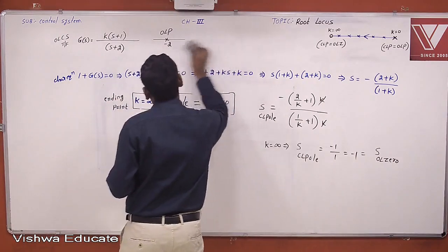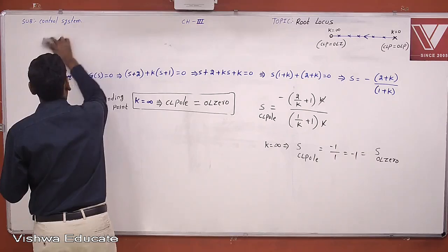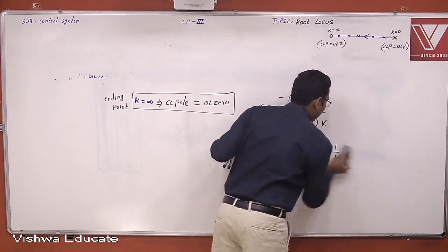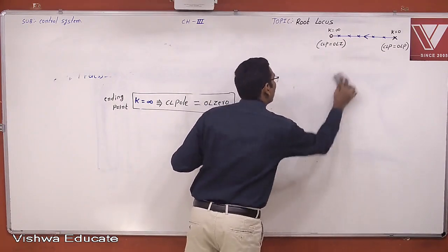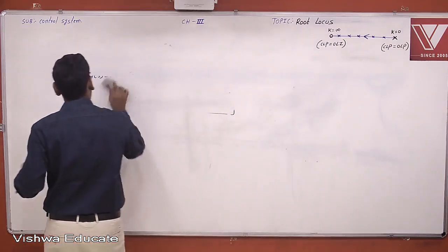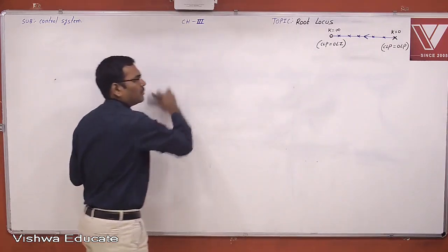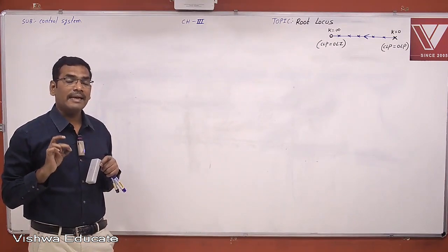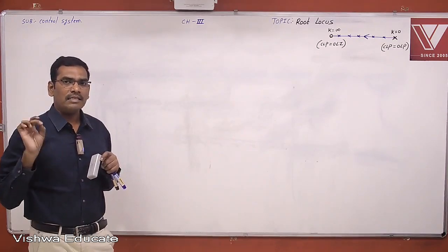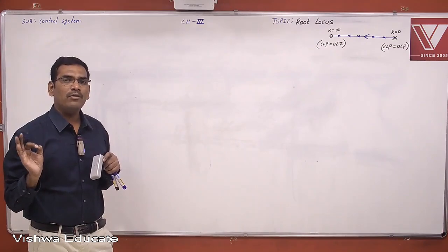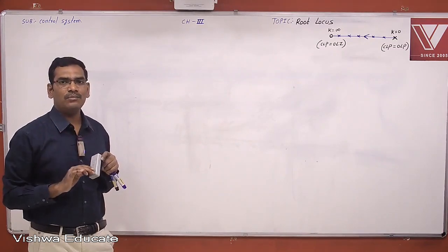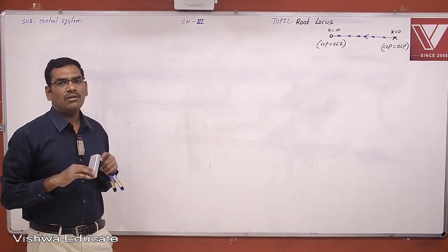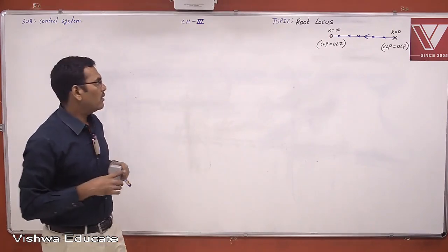So now finally, I think you have an alternate solution for that. Is there any problem in the closed loop? Then you may take directly the open loop transfer function and try to draw the root locus diagram. Okay. So the root locus diagram starts with open loop pole and ends with open loop 0, but the starting point is k equals 0. Open loop pole will be exactly the same as the closed loop pole. The ending point is at k equals infinity. Open loop 0 is exactly equal to the closed loop pole. So the derivation part also will be covered. Okay.